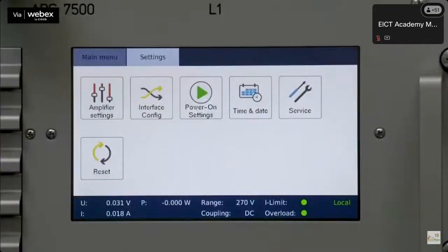In this hardware demonstration, we have used Opal RT to control the power amplifier to emulate the DC bus voltage. Here, an external voltage signal is given to the analog input of the power amplifier in proportion to the required DC bus voltage.